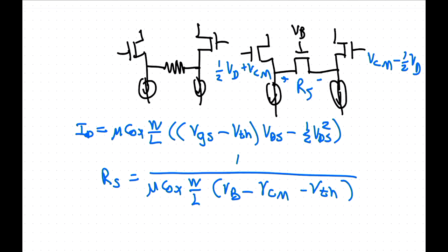In the triode region, yeah. I don't think it helps. In fact, I think it might even make it more restrictive, because you need to make sure that both the transistors are in the triode region. So I don't think it'll help. It's a good question though, because sometimes transmission gates are better than single transistors. Anyway, we can make it tunable.